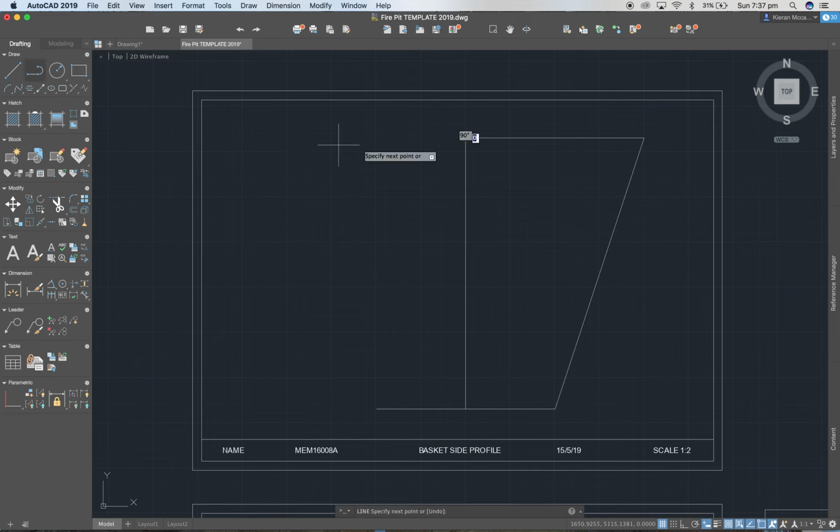We are then going to repeat that for the second side. Again, that with 200, and this time because we're going the opposite way, it'll be 180 instead of 0. We'll have that there like so, and then we're going to close it down again like that. Just press enter there. I'll let that delete. I'll just snap that back into place. We'll have that there. Now I don't need this centerpiece, I can take that away. Just click on it and then just press delete like so. So now we should have this outside shape, which will represent the side profile of the four sides of our baskets.